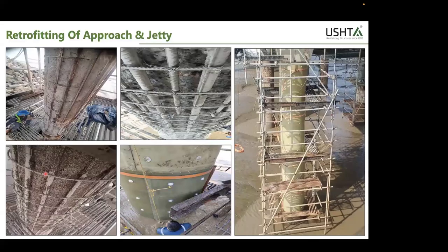So that's the purpose. Further, what we did was we fixed sacrificial anodes on this. Sacrificial anodes can be of many types. It can be a hybrid anode or a normal anode. What it does is, if you've seen the chemistry table, zinc corrodes before the steel corrodes. So whenever there is current flowing, it will flow through zinc and not through steel, and zinc will sacrifice itself before that. So it is known as sacrificial anodes.